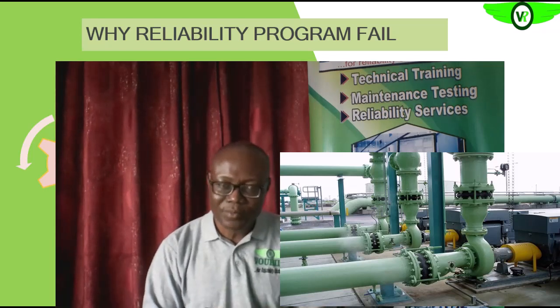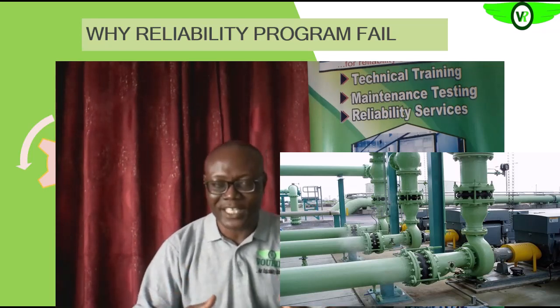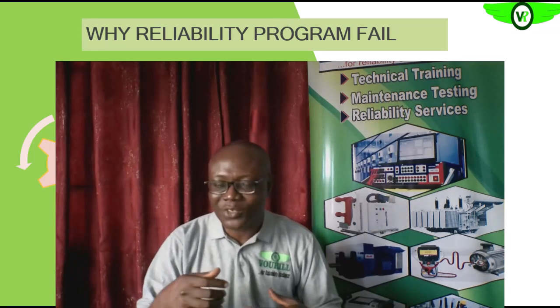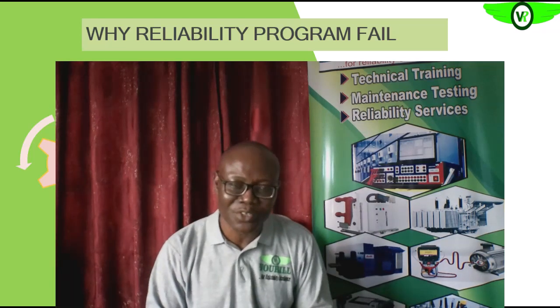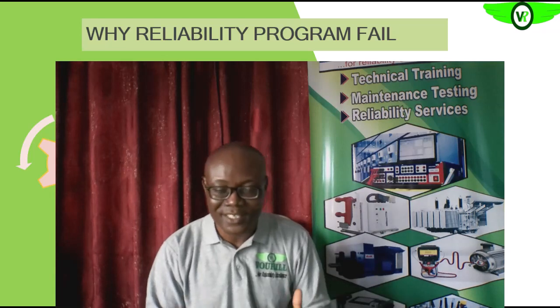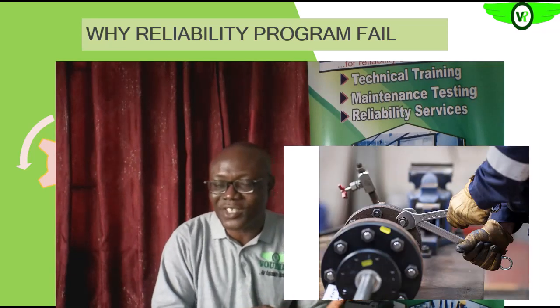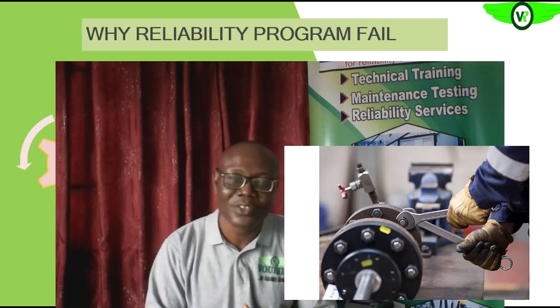You will see that if technician A, who has more strength, comes to do that installation, the tendency of him torquing those bolts close to or even more than the actual torque is there, than technician B, who has less strength to actually torque those bolts.